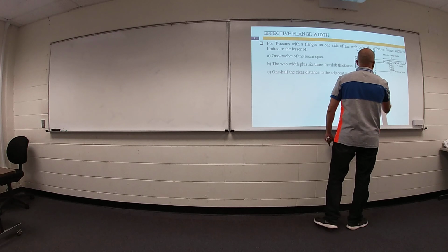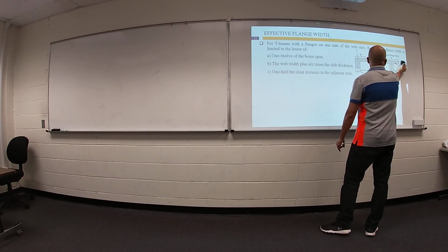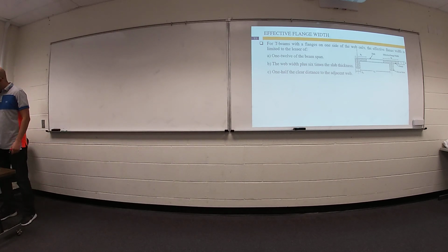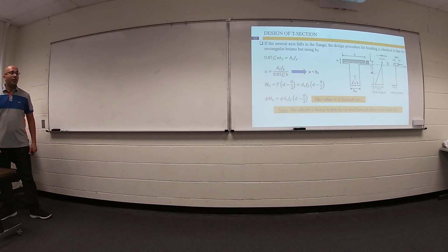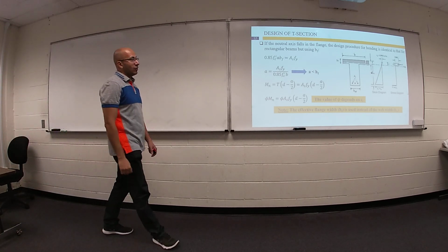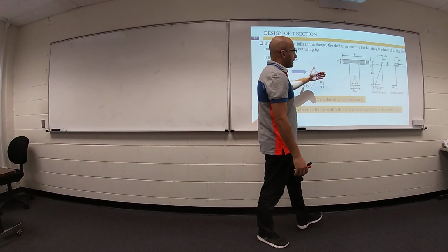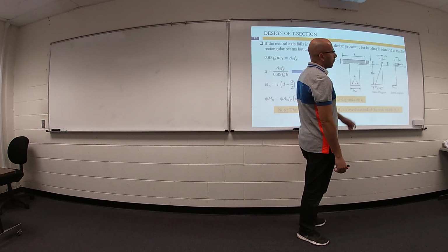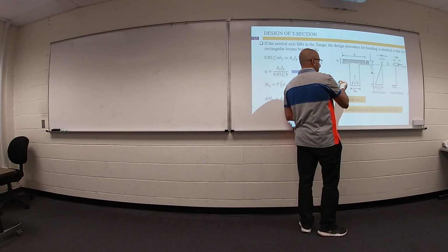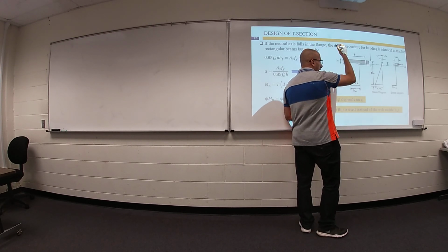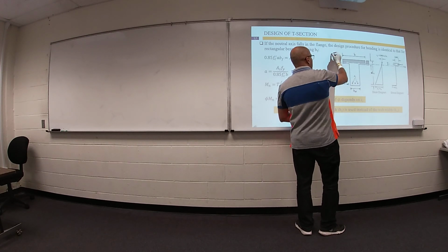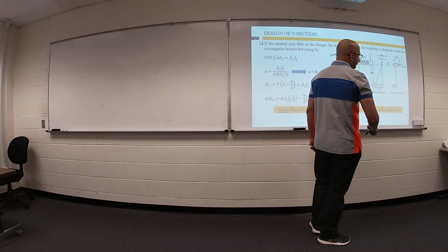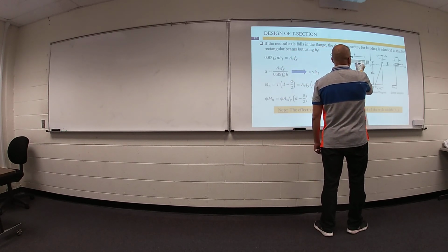Last time we started with the first case. Anybody remember what was the first case? Where the neutral axis. Yeah. The story that we learned from the beginning of this course. What was the story? We have a cross section. We have in one side steel reinforcement. That means we have tension. On the other side, we have compression. In between, we have something called neutral axis.